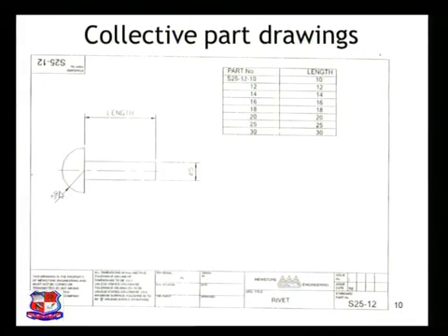Here 5 is written, and length. So this length is say L, and if these are the standards of the product, for example, let me pick up one, S251210. It means that if this is the specification, this length would be 10 millimeter as shown over here. If the part name is S2512-12, then this length will be 12 millimeter. If 14, S251214, then this length would be 14 millimeter, and so on.